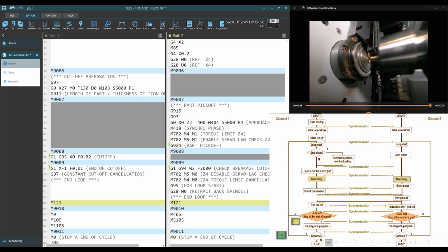If it is on, then rotation stops, all rotation stops, coolant stops, and we can open machine door to check part dimensions or to remove chips. If we haven't pressed reset button, then we can resume machining by pressing cycle start, and then the jump to the beginning of a loop is executed. Otherwise, there is the end of a program.